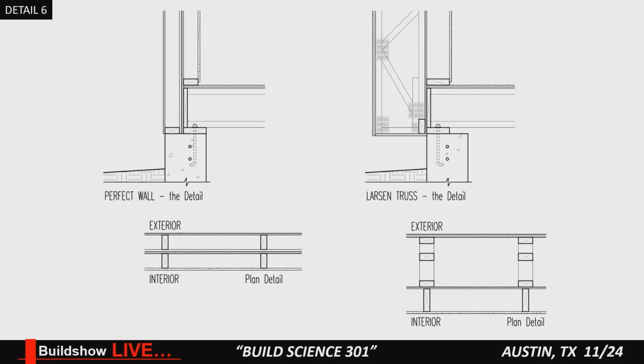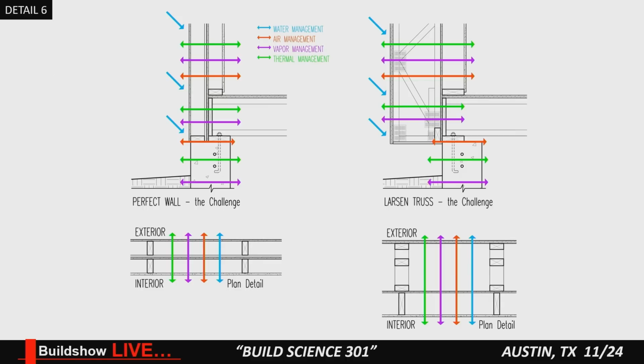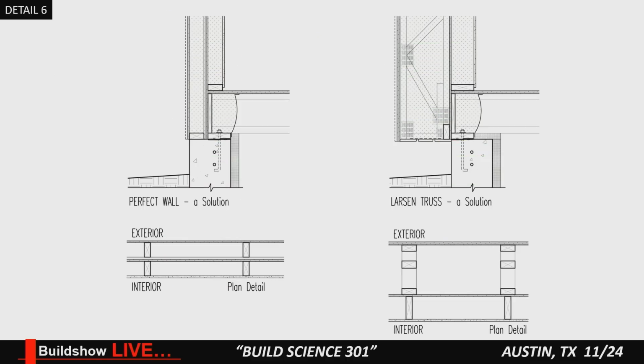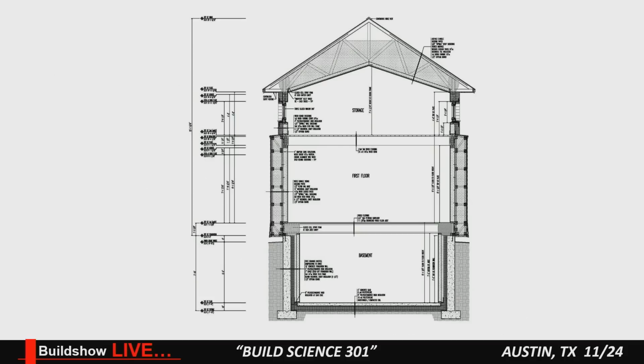800 square foot passive house. We didn't want to make a really super thick wall because we only had 800 square feet we were restricted to. So I told Farley, it's easy. We'll just figure out a way to insulate outside of the foundation wall. So we hung a 14-inch floor truss on the outside of the wall. Pretty cool. You can see all the challenges here, but there you have the details. The section's quite impressive. Like I said, 14-inch floor trusses hung on the outside of the wall.